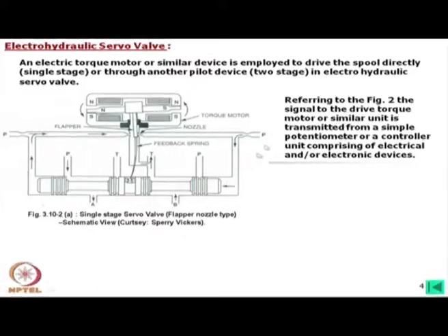However, on the actuator there will be a position feedback or position velocity transducer, sensors, that will again be fed into this machine, which will make some more corrections to make this valve accurate. But a servo valve may not need the feedback from the used point.